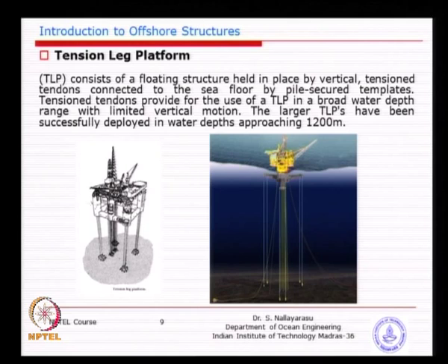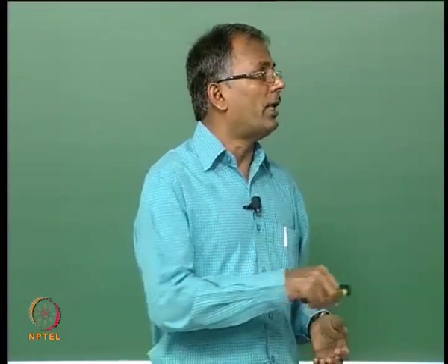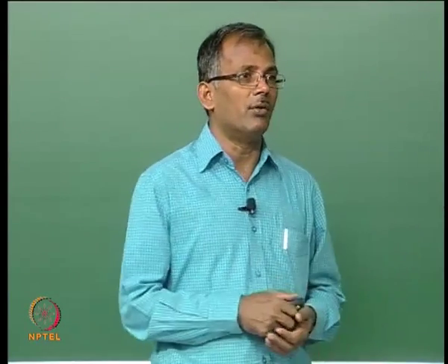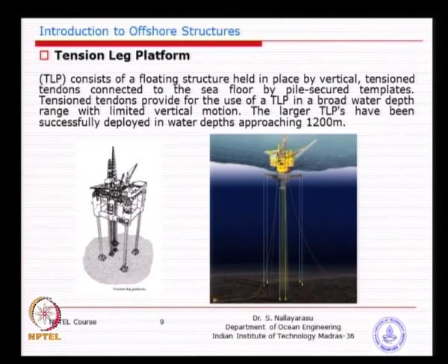On many occasions in the literature you will find tethers are mooring wires, typical mooring wires, but in recent cases we actually have structural members, large diameter tubes attached to the hull as well as to the ground, which gives you a little bit of horizontal stiffness also, and at the same time you have a positive buoyancy which always creates tension at the hull, in the tether line. So, this variation, the second one, is basically a mini TLP, which has a very similar function.